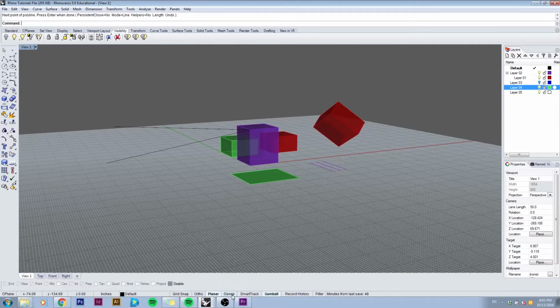The next one is O-snap. O-snap is what you will use a lot since it has a variety of options. If I turn it on, you can see all of them here. Look for these carefully and try them all out. Make sure to only keep on the ones you're using, since having too many on becomes overwhelming and difficult to find the perfect snaps. I'm going to turn all of mine off.